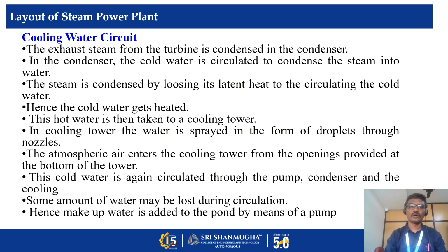Then the cooling water circuit. The exhaust steam from the turbine is condensed in the condenser. In the condenser, cold water is circulated to condense the steam into water. The steam is condensed by losing its latent heat to the circulating cold water. Hence, the cold water gets heated.